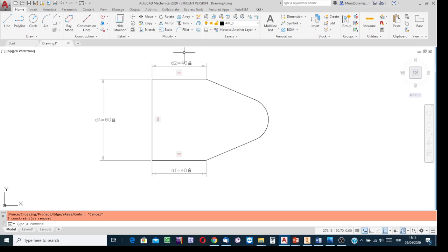Right, so we need to apply the region definition process. Okay, expand the drawing panel and find the region definition button. Start the process and then say that this and those are the boundaries of the same region. Indicate this, indicate the others, or use the windowing method, select all, press enter. And then yes, you see I added this boundary as a continuation of the others.